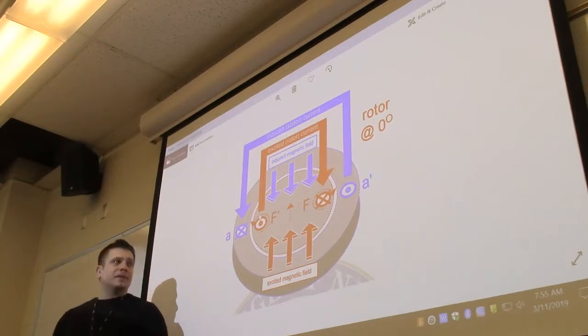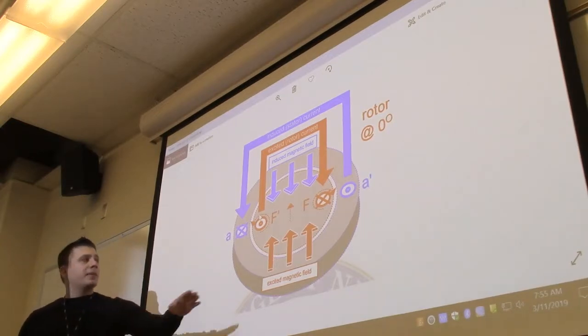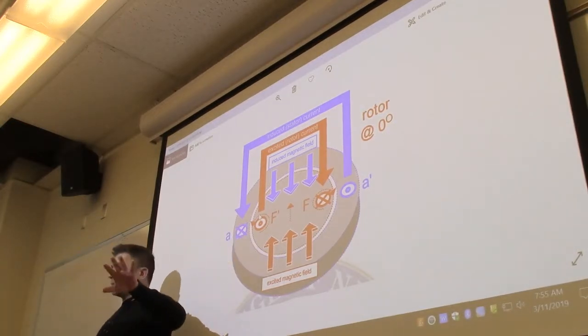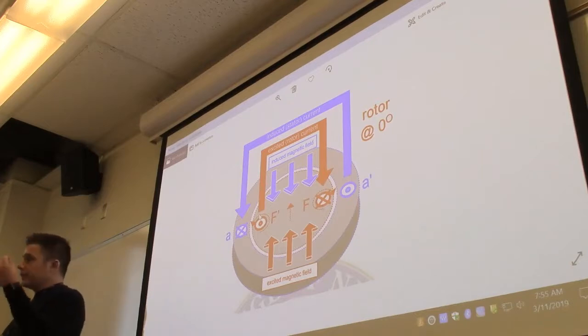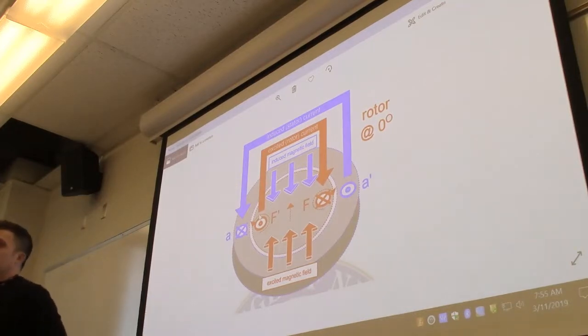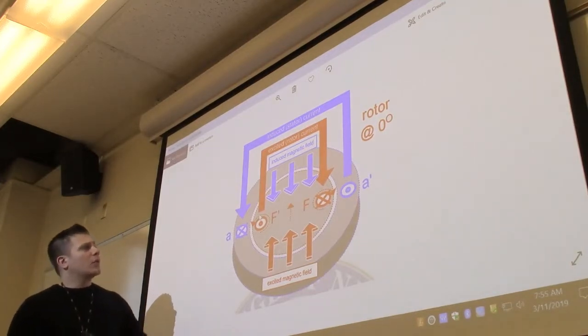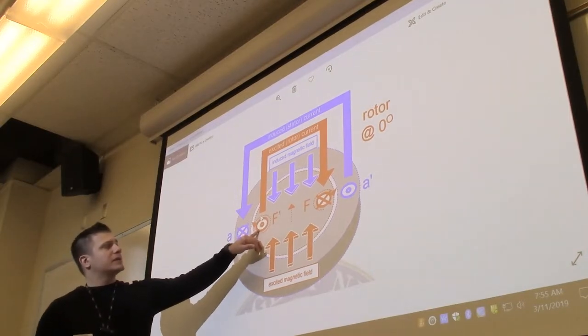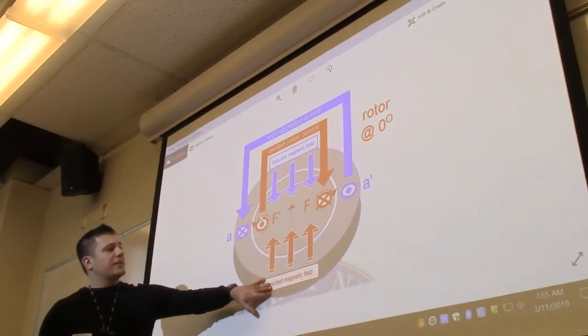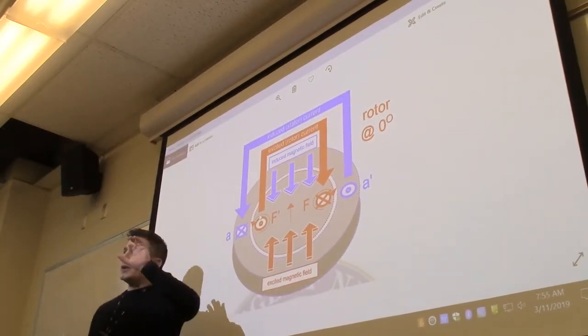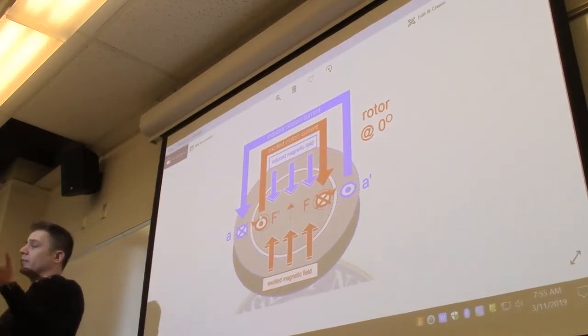And usually, what happens is beyond startup, some power that's being generated by the unit will be siphoned off, run through a rectifier, and used to excite the field winding. So we run current through the field windings, which causes this magnetic field, our excited magnetic field. And because we rotate the rotor,